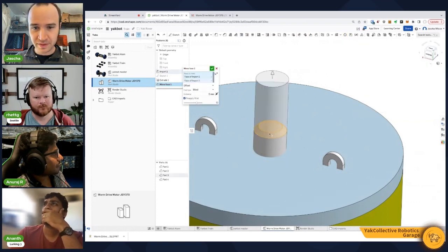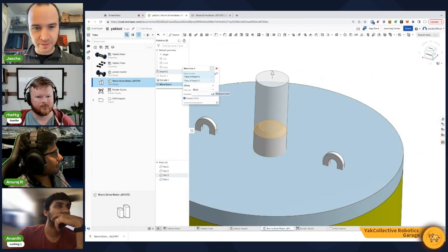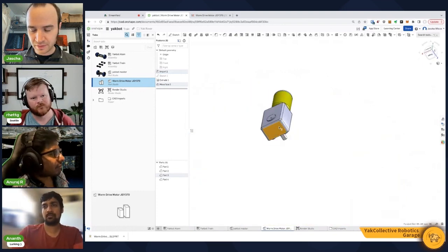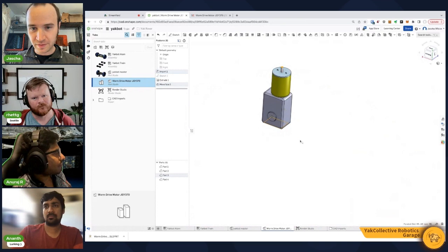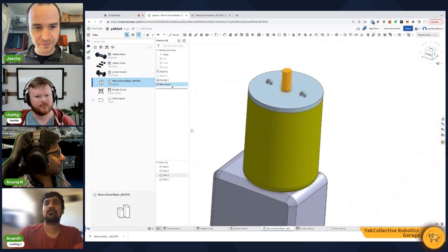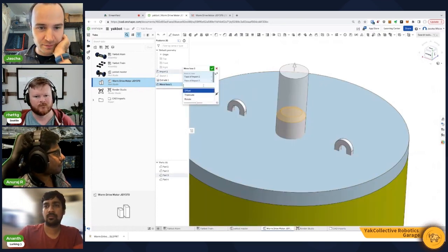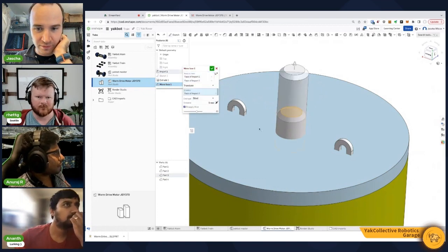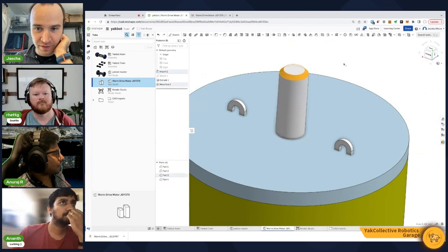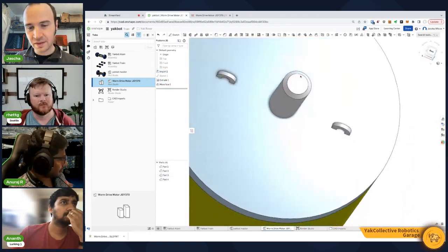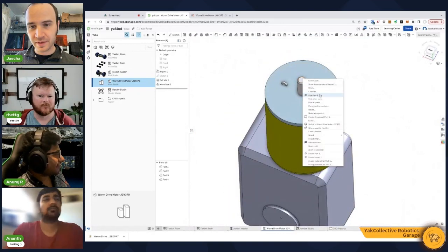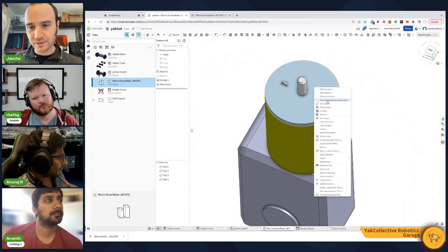So we'll do a move face. And we'll take this shaft and make it longer by 4.8 mm. Okay, so now if we measure this, 85.6, and I measured 85.5, so that looks good. The chamfer didn't get moved. So we want to translate this, not extend. And we'll make this face. That's correct. We want to keep that chamfer. Okay, very good.